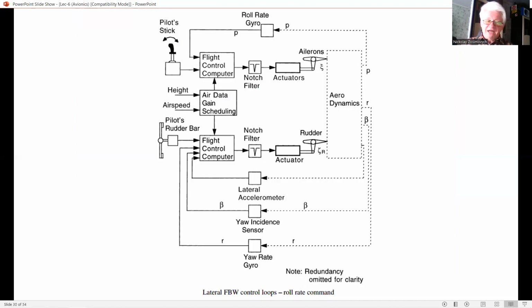The subject of handling characteristics and PIO involves very considerable background knowledge, and it is only possible within the space constraints to give a very brief overview. The control exercised by the pilot is influenced by the following factors. There is an inherent time delay of the order of 0.3 seconds in the pilot's response. The pilot's control sensitivity or gain, however, can be varied, and the pilot is able to provide a phase lead to compensate for the aircraft's response.